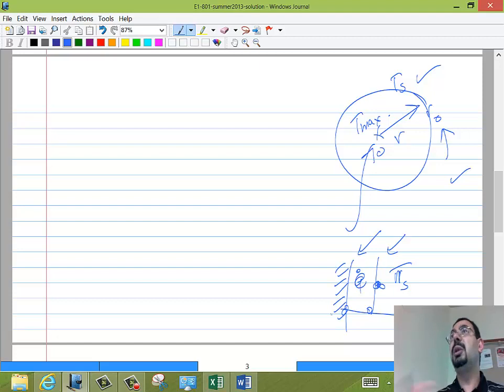There is nothing in the middle so special that you can put your hand on its temperature or its gradient. So for that cylinder, if you are integrating from scratch, one boundary condition is over here. The second boundary condition needs to be there. It's not that T equals 700 or 800 at the center line, because we don't really know the temperature at the center line. Actually, we are required to calculate that. So what is the other boundary condition?